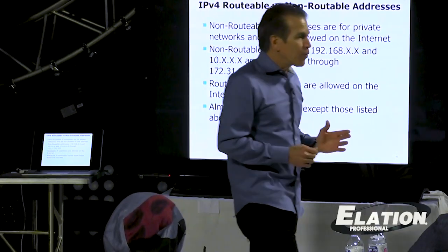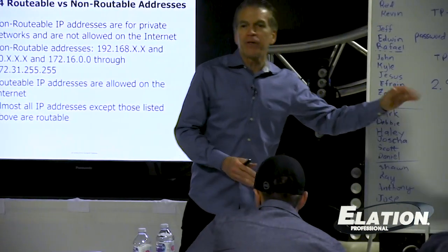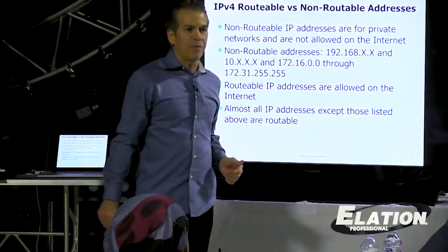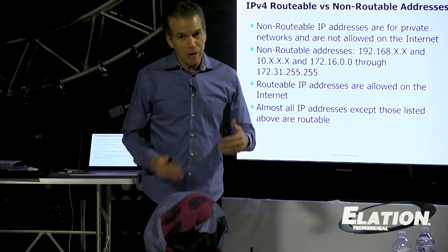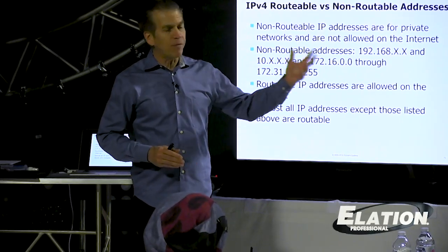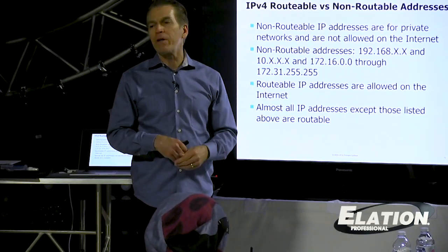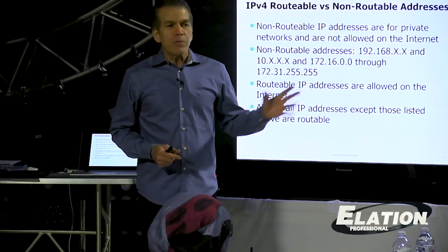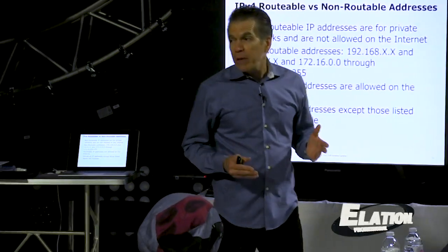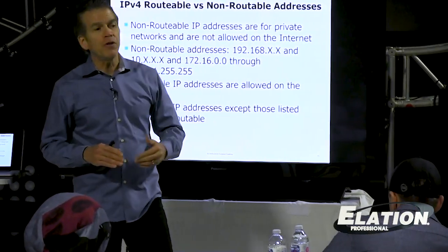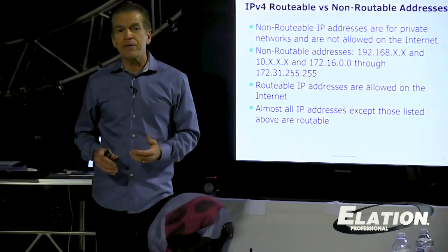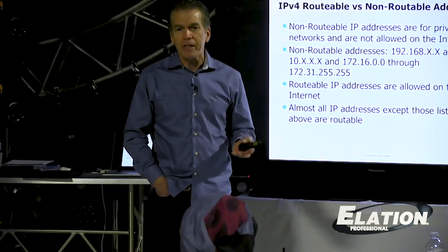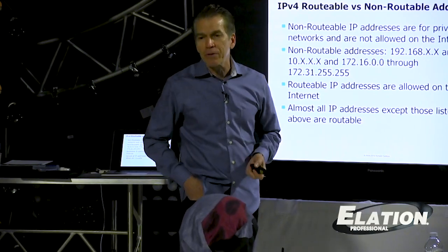But sometimes you're restricted by the fixture to a certain range of IP addresses, either a 2-dot or a 10-dot. So it would be much simpler if the fixtures ran DHCP and would allow any IP address. So that's probably why this particular fixture does not have DHCP, because they want you to use a 2-dot address or a 10-dot address. And I believe that whole approach is obsolete now, because any IP address will work with ArtNet.